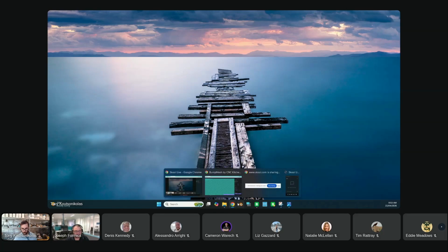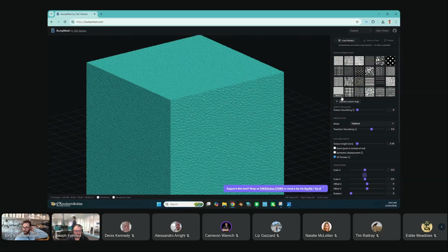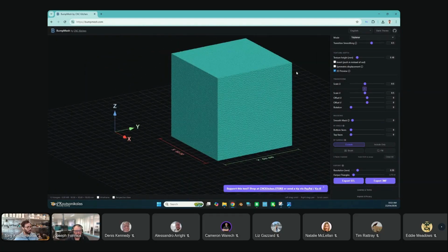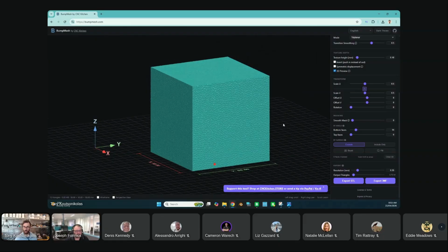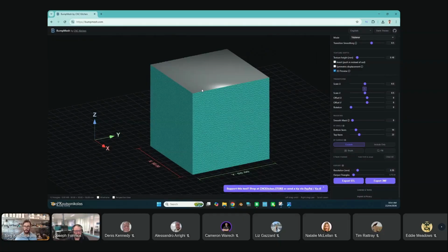But my model didn't quite show that leathery texture as much as I would like it. And this is where we start to get into these other settings. So firstly, the texture on the top and the bottom, let's say I just didn't want them. Say this was a handle or something, and on the top and the bottom, I just don't want the texture. So I can go to masking, and this basically allows me to control it. It's some sort of algorithm that gets applied to it, and basically it's going to be looking for the top and the bottom when I use this slider, and it's going to be hiding it. Where it shows up in gray, it hides it, right?